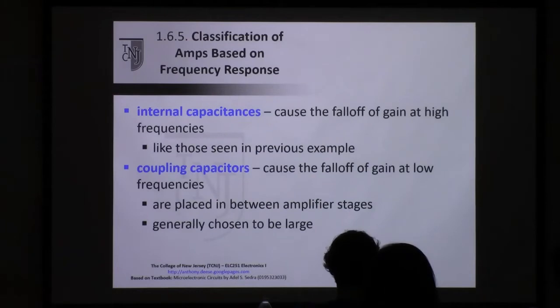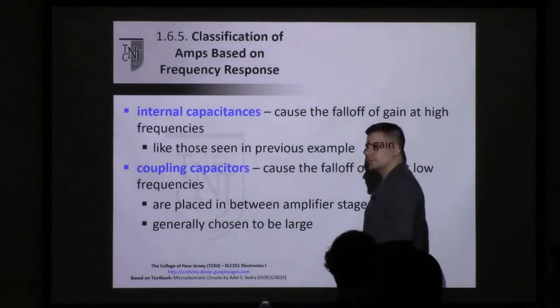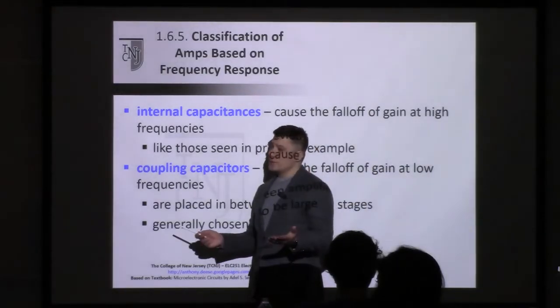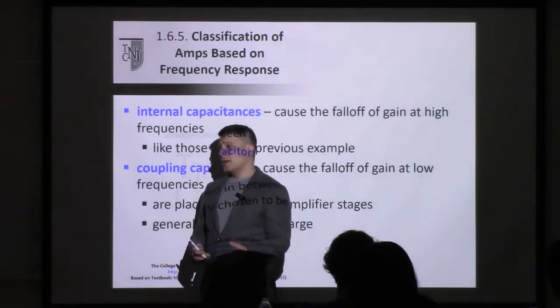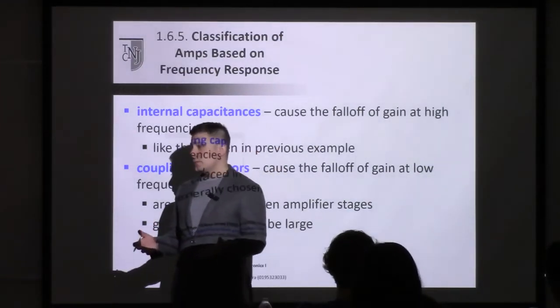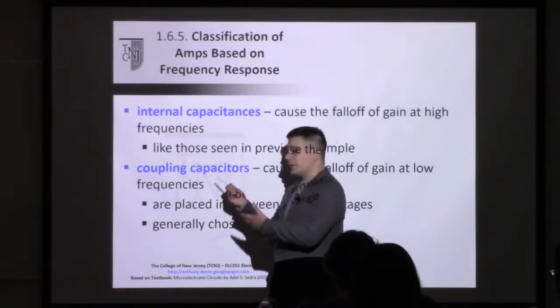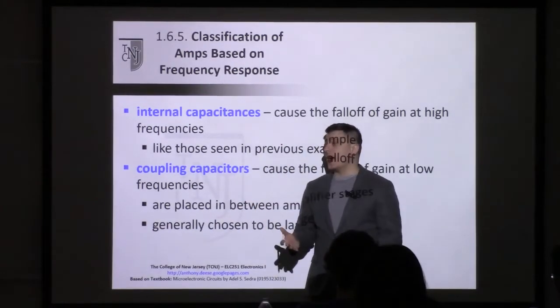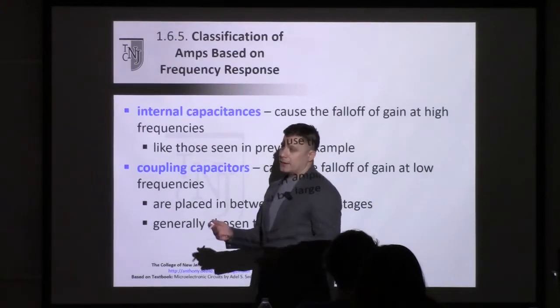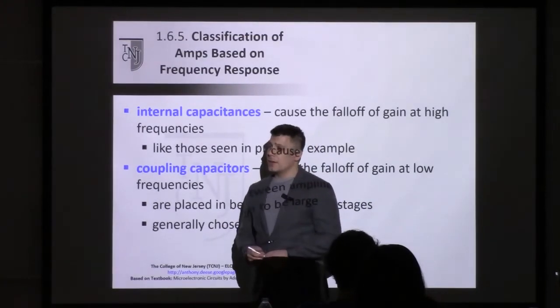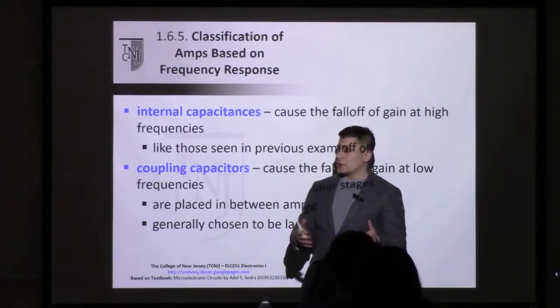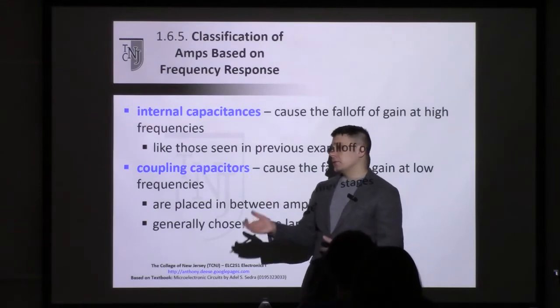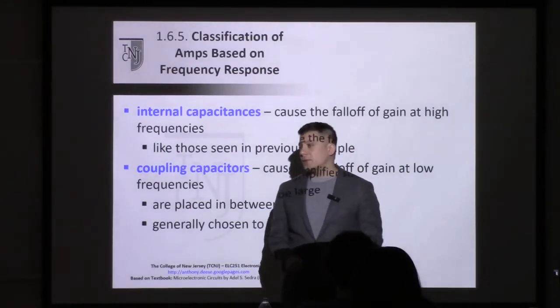Okay. So yes. Just really quickly, is the transfer function of a specific filter usually something that's given, or that we need to find out? Depends on what the problem is. So for example, if it's a low pass or a high pass filter, very basic, then on your cheat sheet you'll have a table for it, and you can just glance at it. If it's something like what we just looked at, you had to derive the transfer function for that one. So, yeah, it really depends. Some problems may give you the transfer function, ask you to work with it, and ask you some questions about it. Other types of questions may just give you the circuit and say, hey, come up with the transfer function.